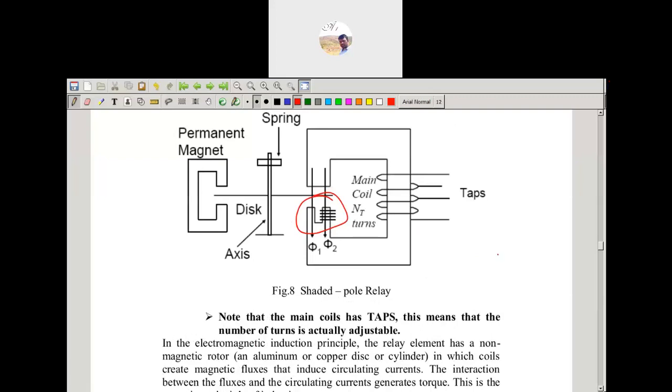So here with the CT, we have different inputs. If the input current is 60 amps at the primary, the secondary shows 6 amps. That is the ratio; the turns ratio is different in the CT. Based upon the current tap setting in this diagram, if there are variations in the CT, then the induced fluxes in the electromagnetic relay vary, and the variation causes the contacts to trip.